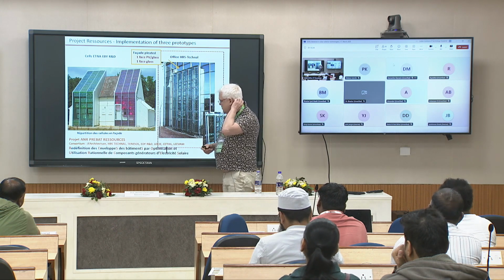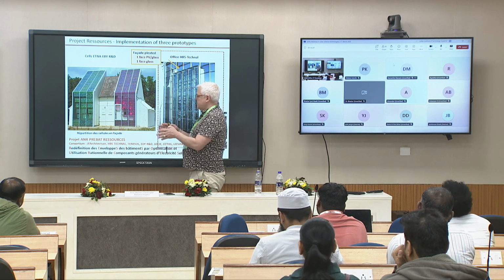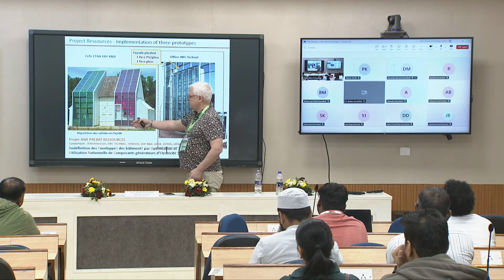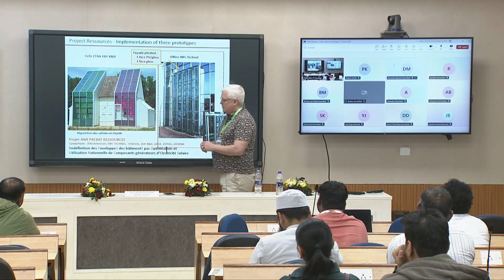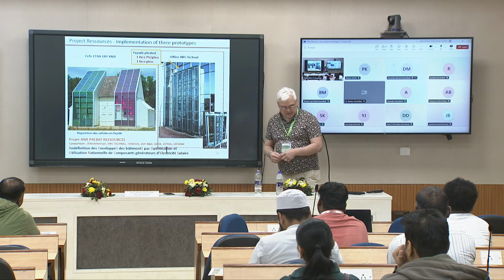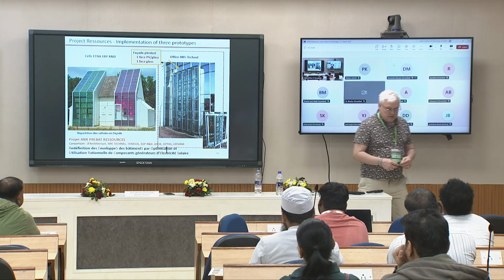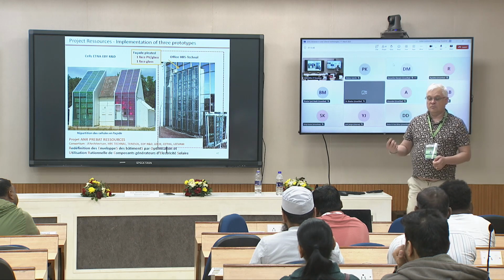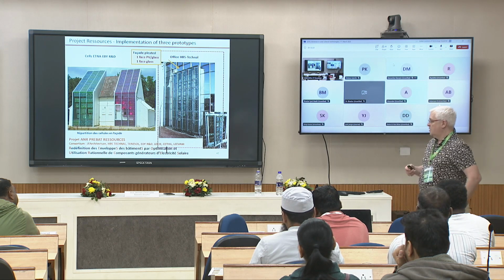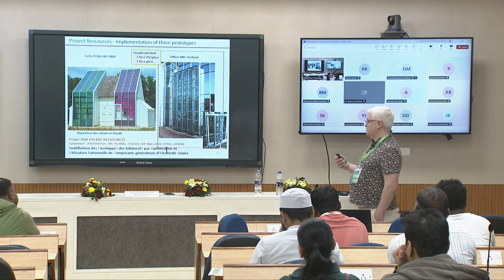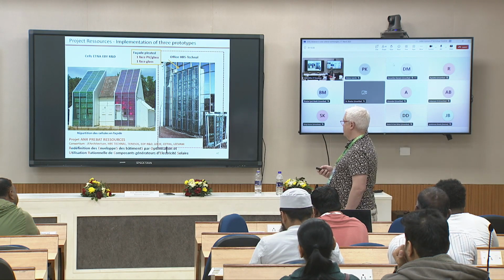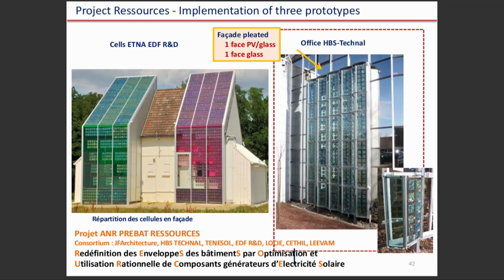We found it was good to have an asymmetrical heating of the first facade and the second one, because it allowed generating turbulence and so improved heat transfer in the air gap. We have also done that for the natural ventilation of this facade, in this existing building, which is an office building of one of the partners.